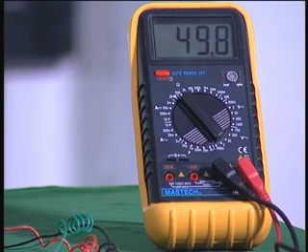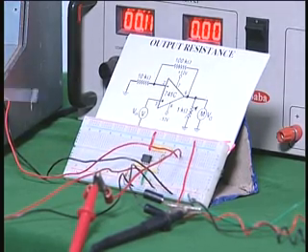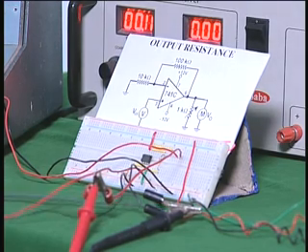So that 50 ohms is the output resistance of this 741 that I have used in the circuit. In the typical table you saw the value should be around 75 ohms, and 50 ohms is actually a good value. Okay, having seen how to measure the output resistance of an operational amplifier by actually performing an experiment,